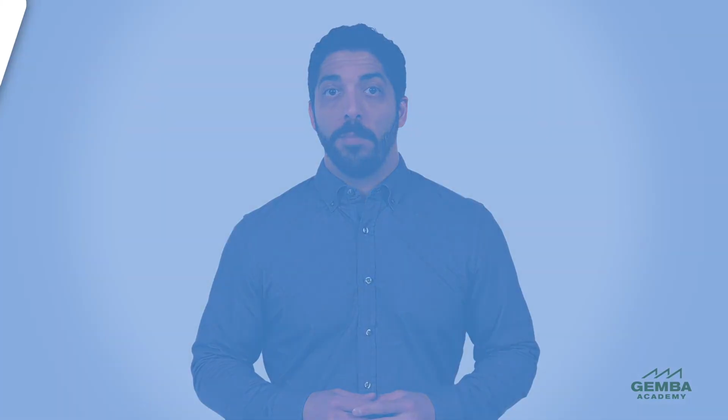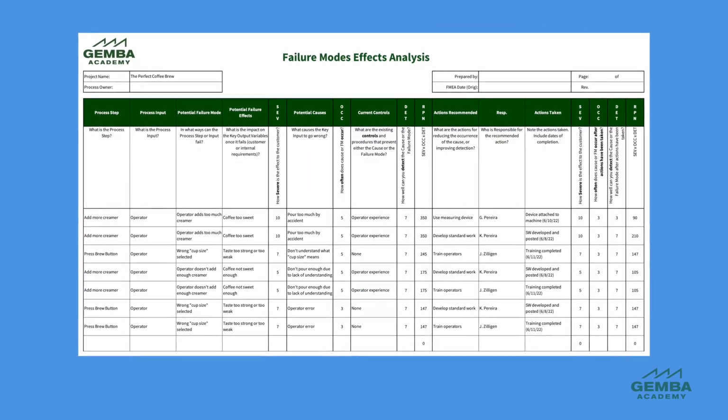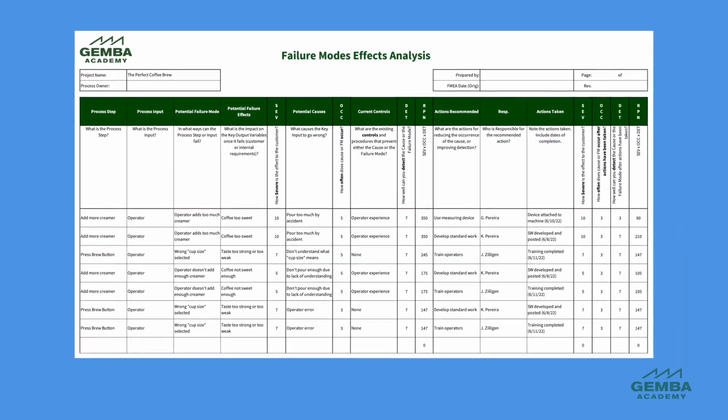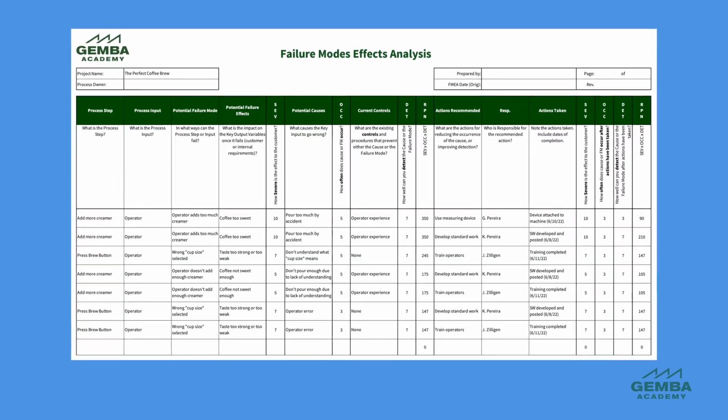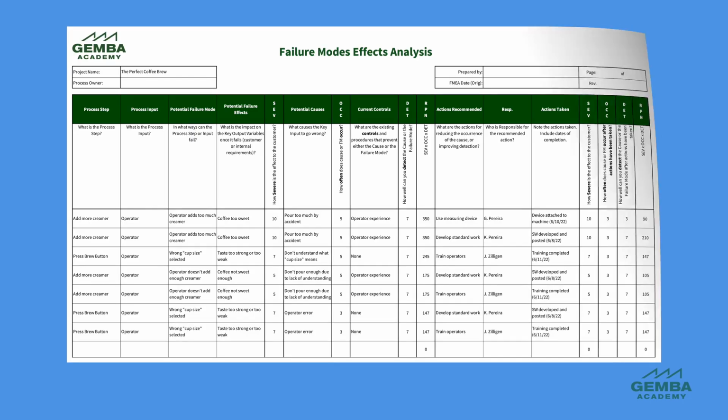The added degree of detail that fault tree analyses provide allows us to focus efforts on improving elements critical to reliability or safety. For example, during an FMEA, or failure modes and effects analysis, we take a bottom-up approach to examine potential failure component by component rather than at a system level. This may identify certain failure modes as being high severity, frequent, or hard to detect. In such situations, the fault tree analysis is useful to evaluate these failures in more depth and with specific metrics.